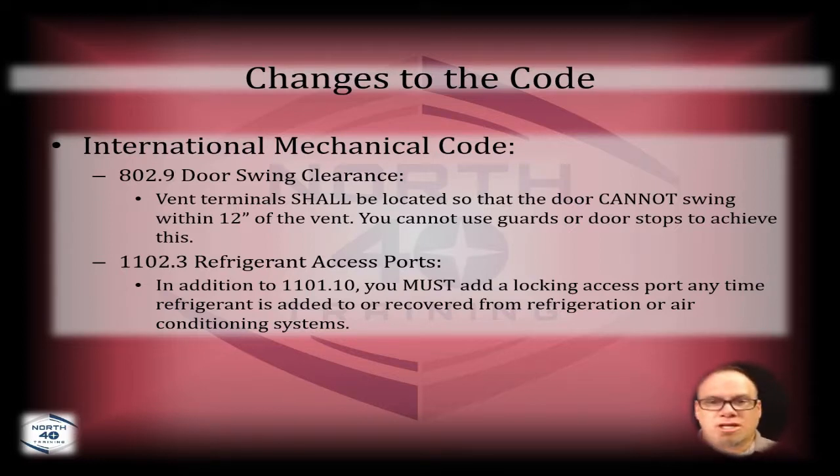Currently, in the 2015 code, they're saying not only if it's accessible to the general public do they want you to put locking access port caps on there, but you don't have to do it proactively. Meaning you don't have to call your whole customer base and say, hey, we serviced you 3 years ago, I want to make sure somebody comes out and puts locking access port caps on there. That's not the case. Right now you can do it as you're doing your service calls. So you go out there, you check the refrigerant levels or your superheat and subcooling, or you make a repair that requires you to put your gauges on. When you leave, you put the locking access port caps on there.